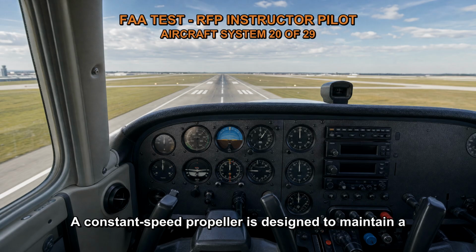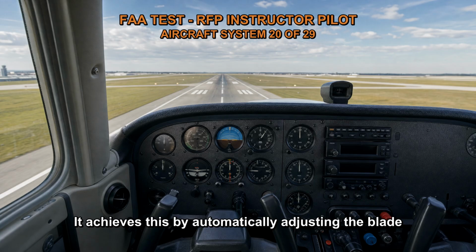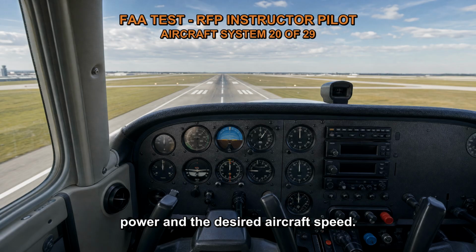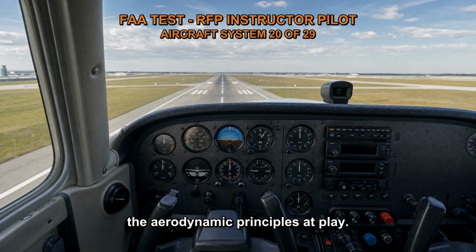A constant speed propeller is designed to maintain a constant RPM, revolutions per minute, regardless of the aircraft's airspeed. It achieves this by automatically adjusting the blade angle to optimize performance based on the engine power and the desired aircraft speed. To understand why a small angle of attack and high RPM are necessary for maximum power absorption and thrust development, we need to consider the aerodynamic principles at play.